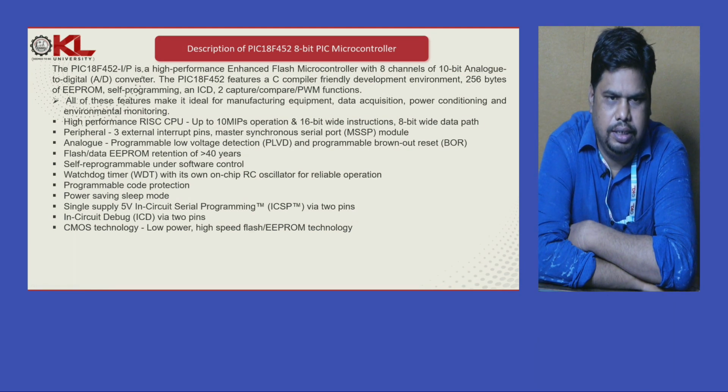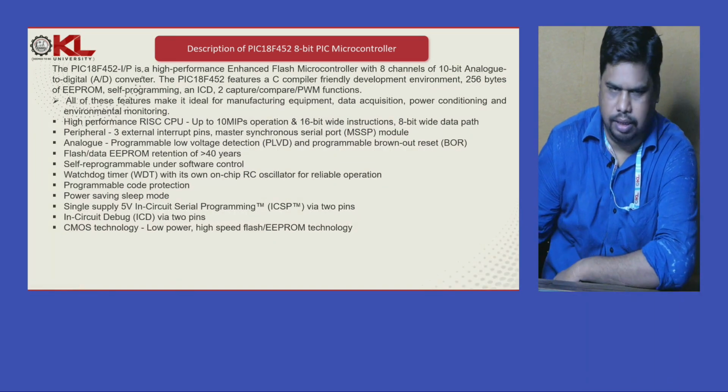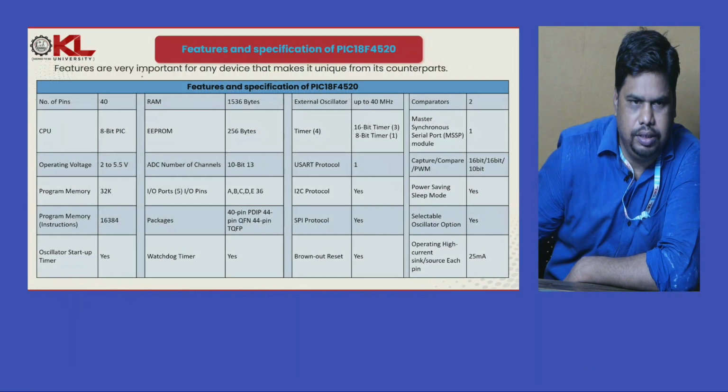Then it has flash data EEPROM retention of more than 40 years, self-programmable under software control, watchdog timer, programmable code protection, power saving sleep mode, single supply 5-volt in-circuit serial programming, then in-circuit debugger, CMOS technology. So this is the terminology, one by one I am going to discuss these features.